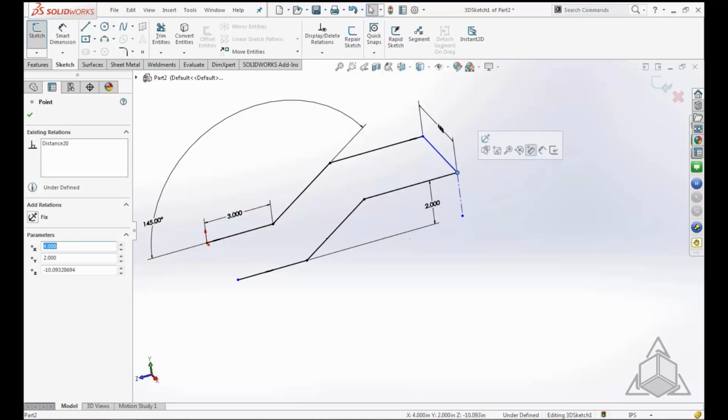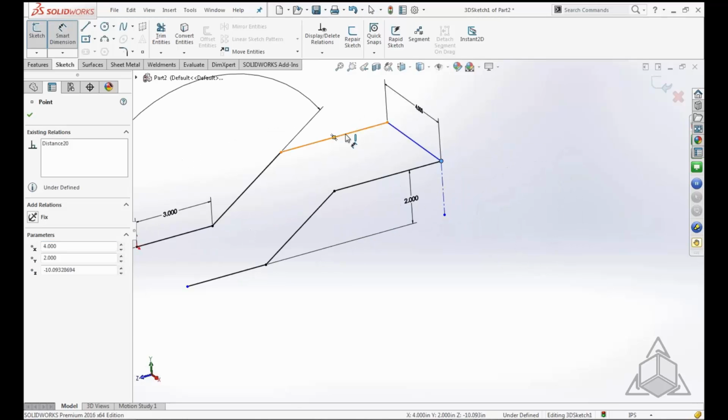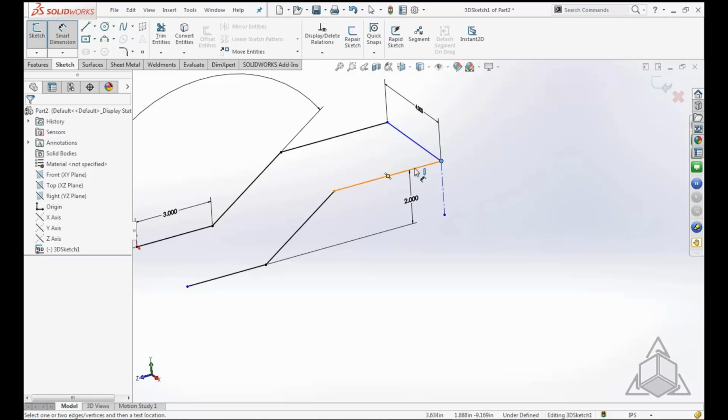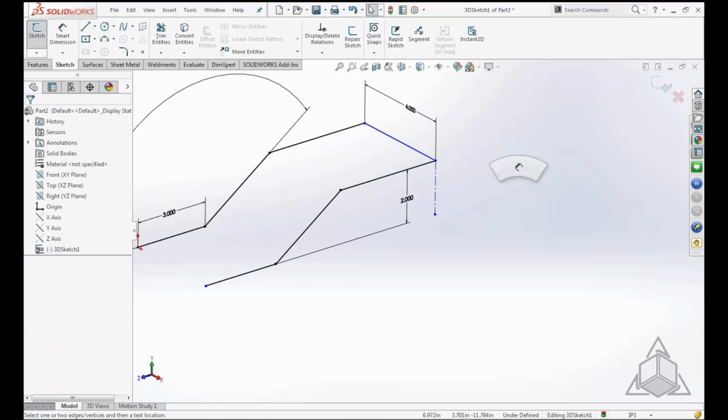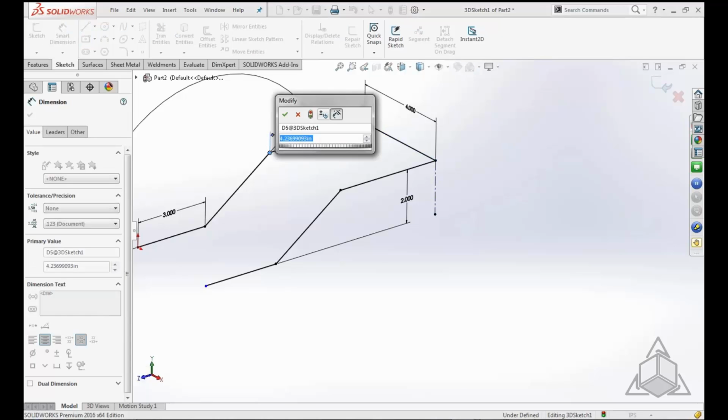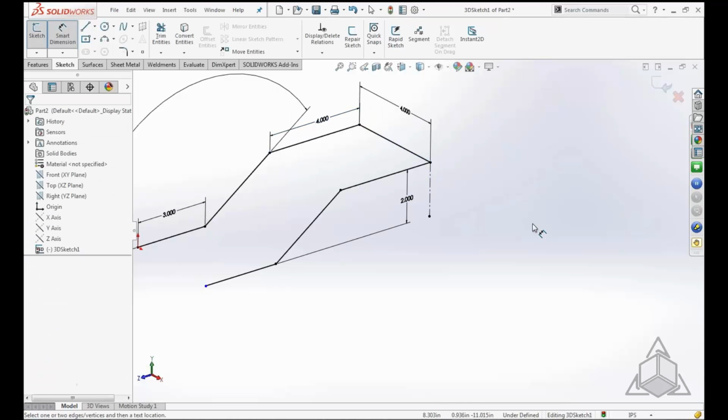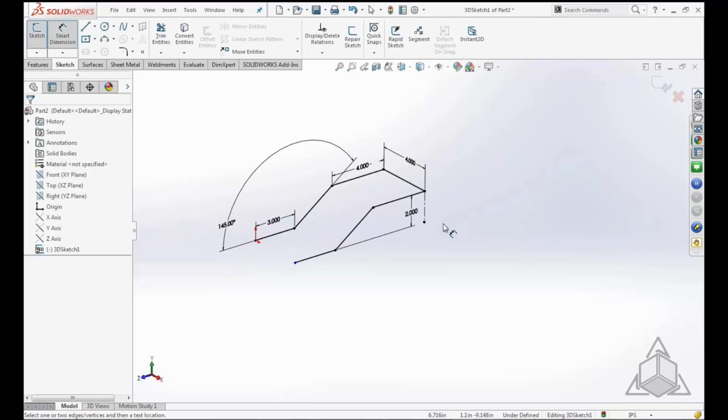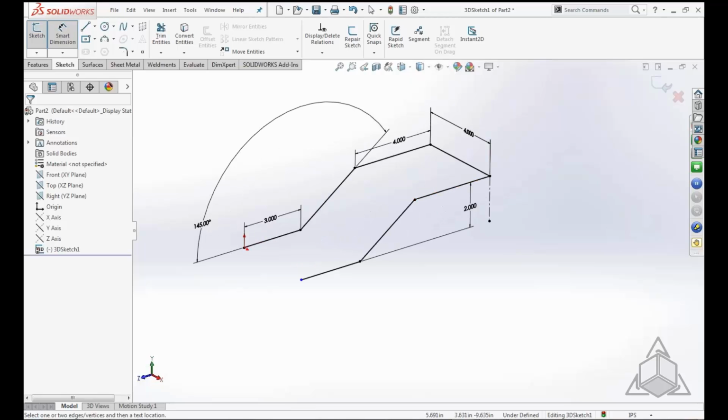Now the last thing I need to lock down in this case is just the length of this edge, which I could certainly put on there as whatever value I want. So I'll use this here as 4. And now I have a fully defined sketch. So in general, other than the space handles and understanding your direction, certainly the biggest hurdle is going to be adding the directional information. Now, I just did that in an isometric view, which is very confusing to most users.